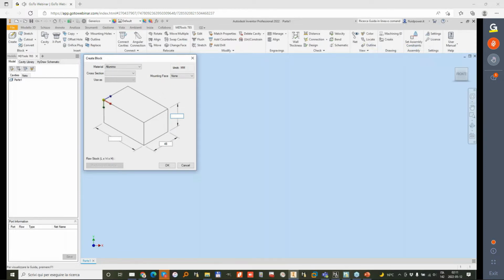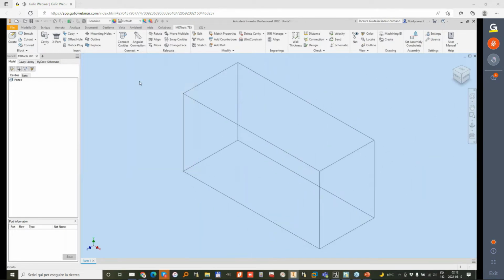So we want this sandwich module to fit into stackable elements. The height may change. Let me put 60 millimeter. Usually this kind of block may become taller if we have many valves. The length may change. Let me put 120 millimeter. Then this will be the biggest variable in our design.